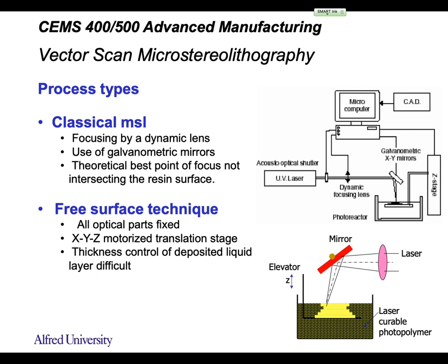Yes. So even though the line width can be really thin, right, if the resolution in x, y, and z axis, if those moving resolutions are not high enough, what's the point, right? So you have to increase this location resolution, right? X, y is controlled by the mirror, right?